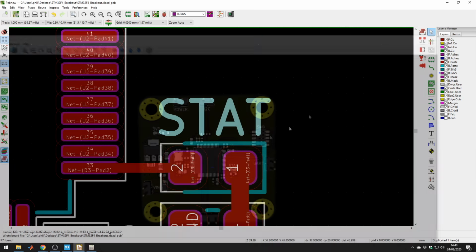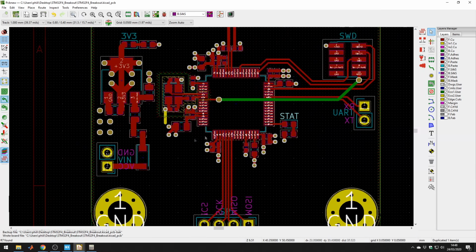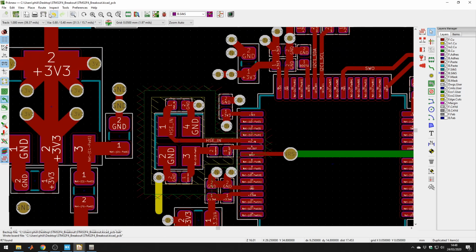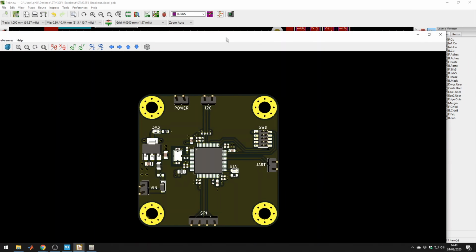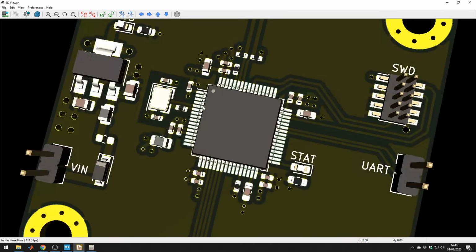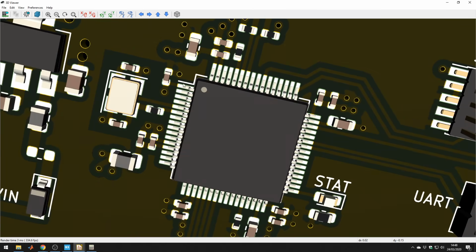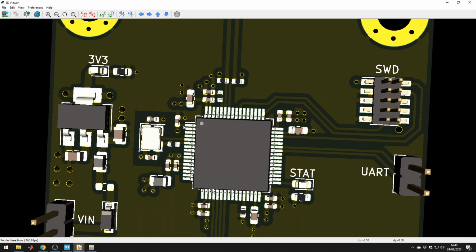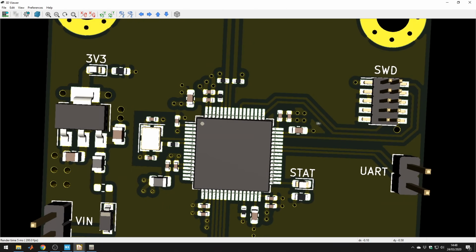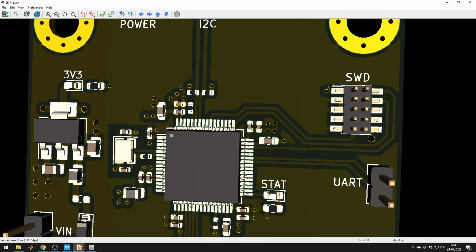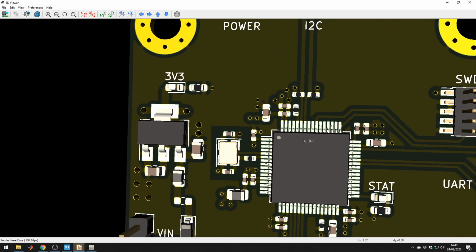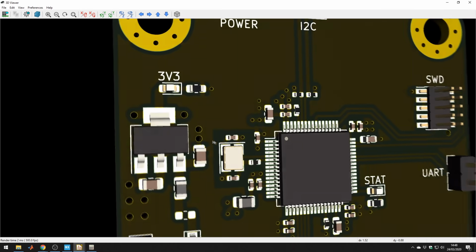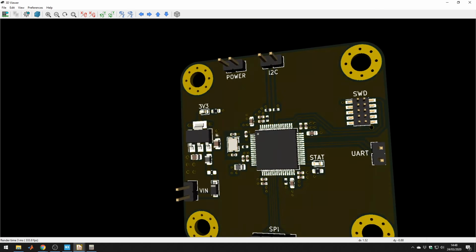Okay, one last thing for the Silkscreen is indicating polarity and pin 1s. As you see for the KiCad symbols, it'll actually tell you, you see this side, the Silkscreen here, indicates that that's pin 1. I tend to always put an extra dot next to the first pins though, just to make sure this is definitely pin 1. Also with this connector, this is pin 1 here, and you can't put the component the wrong way around, but you know, someone might try.